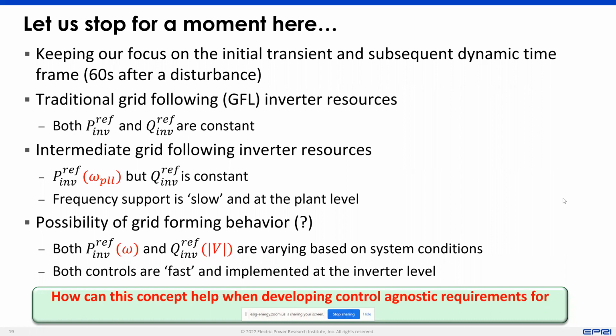Now, the interesting thing then is how a PLL-based control, for example, what Deepak showed, which is still like an improved version of the PLL grid following control that we have today, behaves. If we put that single inverter in a system, in an island with a load, and the load increases, does the PLL give you the signal by reducing the frequency? That part to me is the most interesting, and based on our research at EPRI, we actually showed that PLL is able to sense that load increase by dropping frequency as well. So yeah, that's the interesting part, and it depends on the control loop.